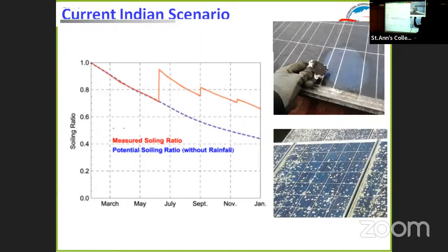under the sunlight at a different level, like a roof or a ground-based installation, and slowly on these panels dust is deposited and accumulated on the top surface. Just as we clean a windshield every day, this also needs to be cleaned to keep it efficient. Otherwise, this dust sitting on the front side, on the cover glass, disturbs the incoming sunlight. So sunlight may not be able to reach the solar cells, and therefore the power production capacity gradually decreases as a function of time.